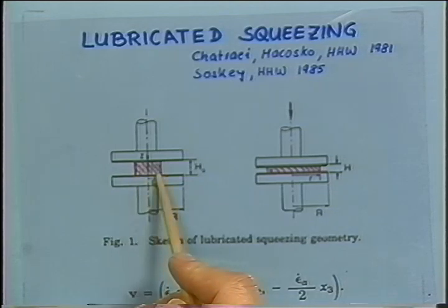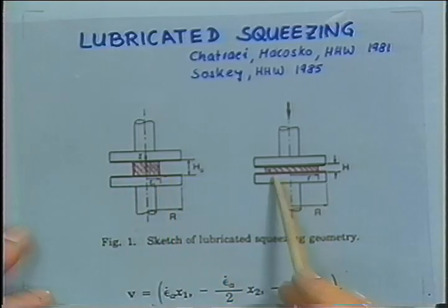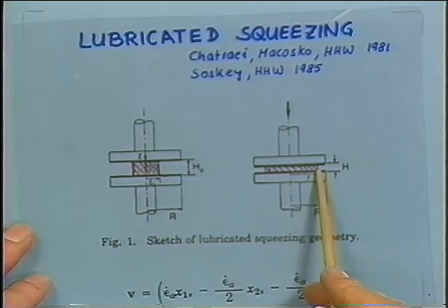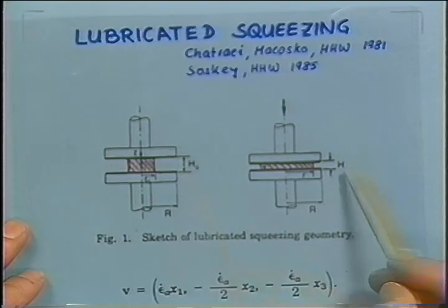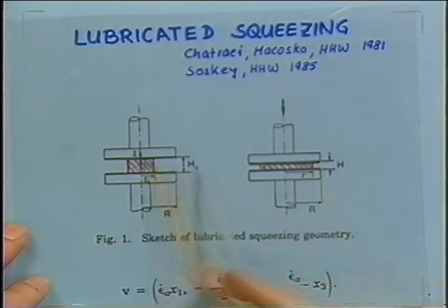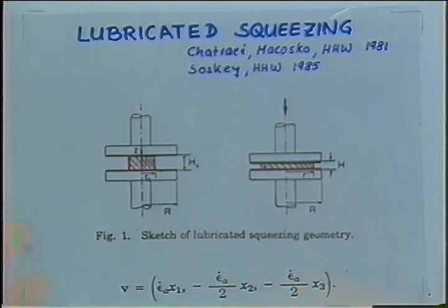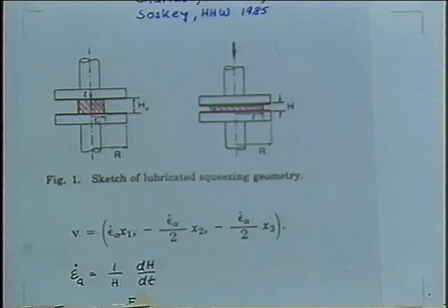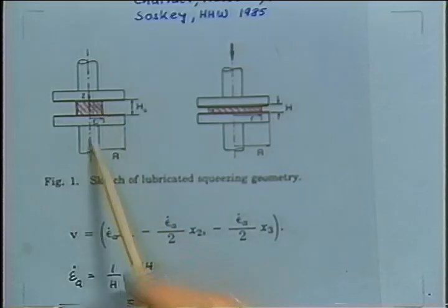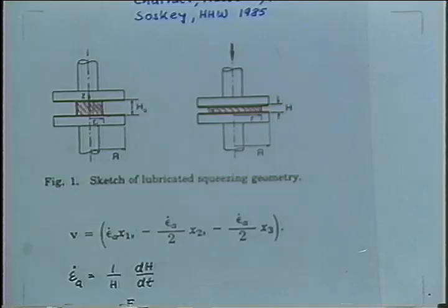And we are squishing our sample from an initial radius to an intermediate radius drawn here, and we measure the height change, h0 to h, and by conservation of mass, we get all the changing geometry. The velocity field is given by the approaching velocity of the plates, and we can choose now an exponential function for this kinematics and introduce a constant extension rate.